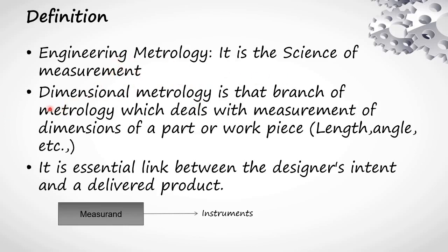In addition, dimensional metrology is that branch of metrology which deals with measurement of dimensions of a part or workpiece, for example, length, angle, etc. And it is an essential link between the designer's intent and the delivered product.